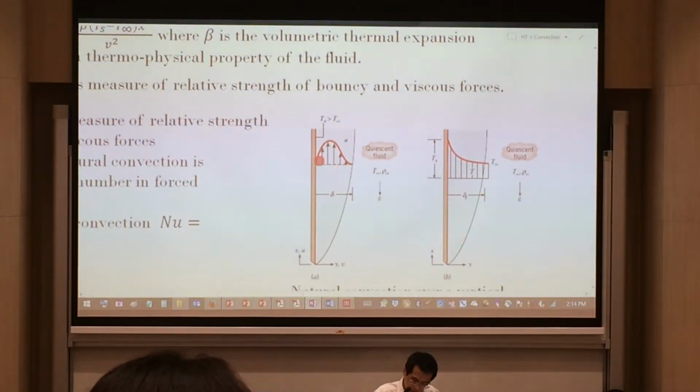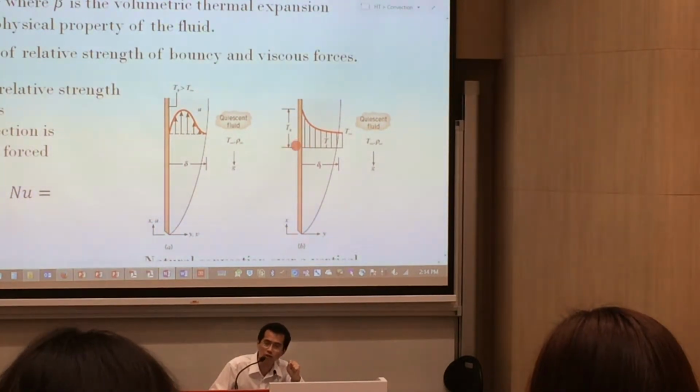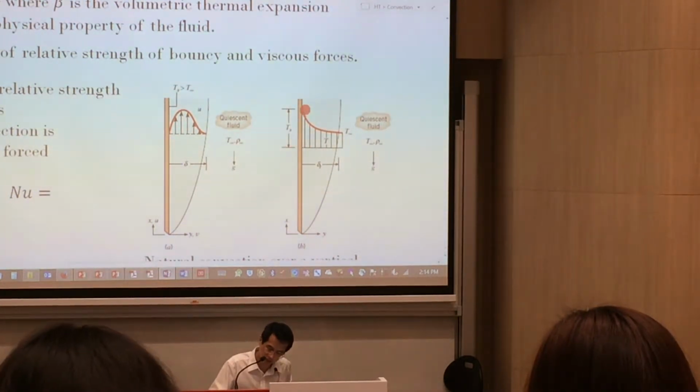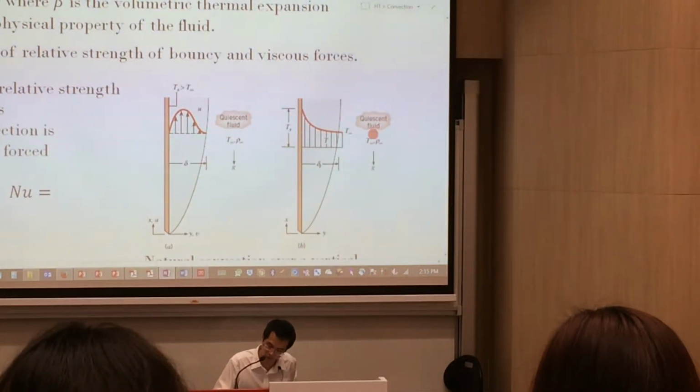And because the velocity near the plate is zero, that means the air molecules over there will inherit the temperature of the plate, and that's why we have a hotter temperature here, and then you will get lower and lower into the ambient quiescent fluid.